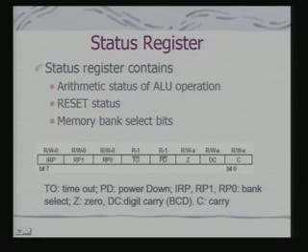See, what we have is that when an operation takes place, the result which goes out from the ALU has to be stored in some register. Which register it is to be stored in depends on the D bit. There is one particular bit in the instruction word which is called the destination bit.